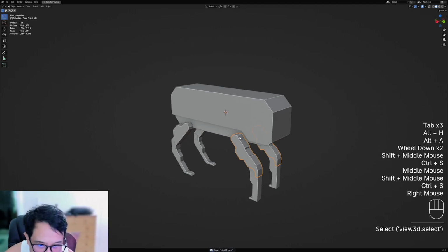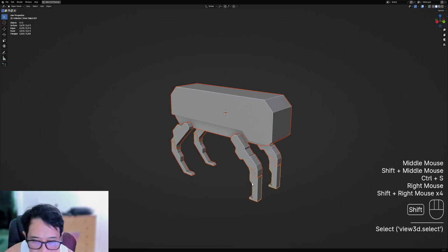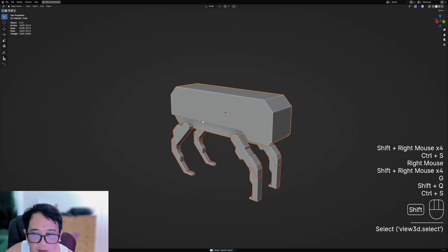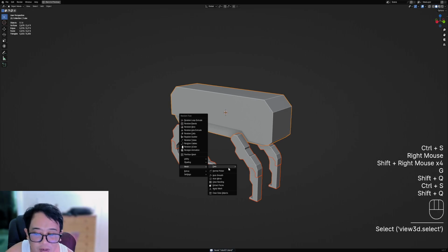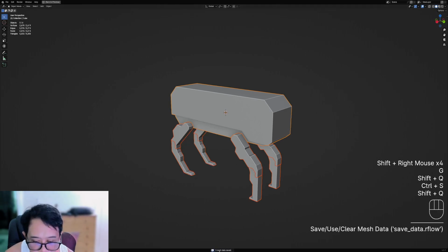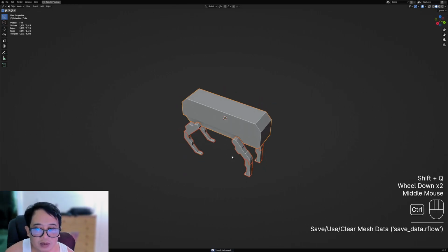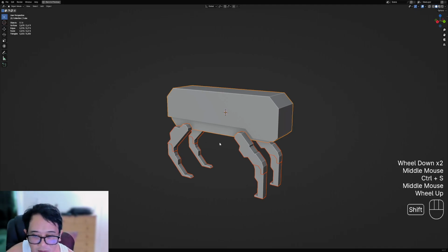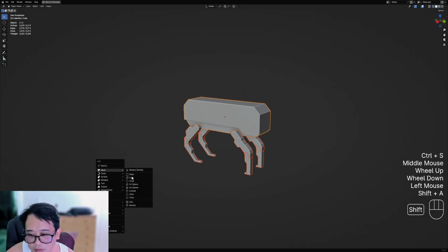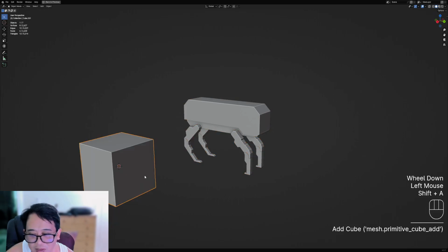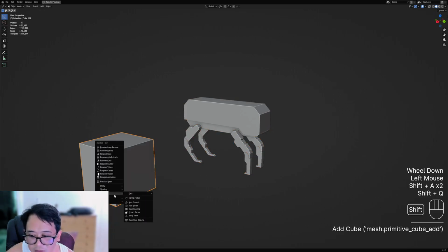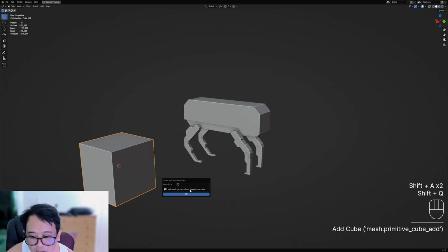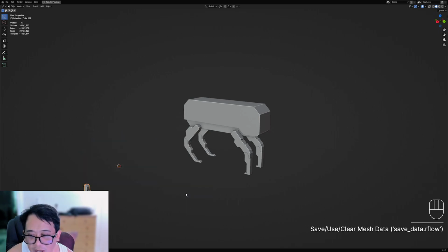Now save this data. 1, 2, 3, 4. Look, mesh. This can operate on multiple objects selected. Save. So mesh data save. And when you save Blender, those get saved in the file. And if you open Blender up, you can reuse that data by selecting an object and then using data, match geometry from saved mesh data. Let's see. Okay, it's the foot.